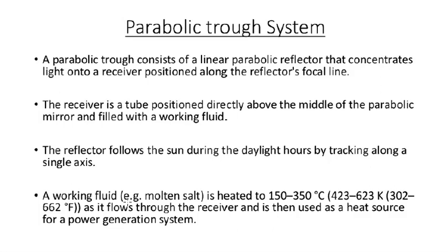It is also possible to produce superheated steam directly using solar collectors. This makes the thermo oil unnecessary and also reduces cost, because the relatively expensive thermo oil and the heat exchangers are no longer needed. However, direct solar steam generation is still in the prototype stage only. So coming to the trough power plant efficiencies.